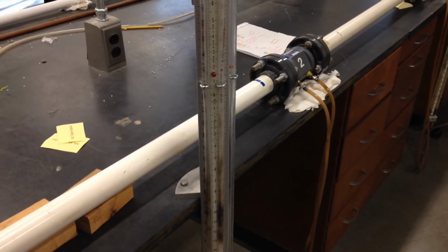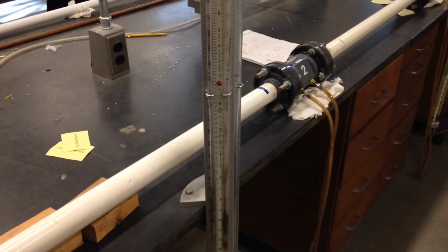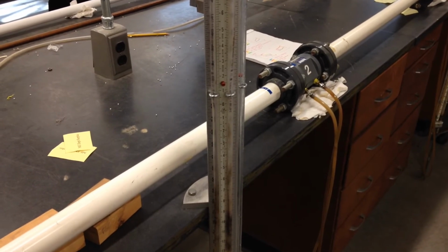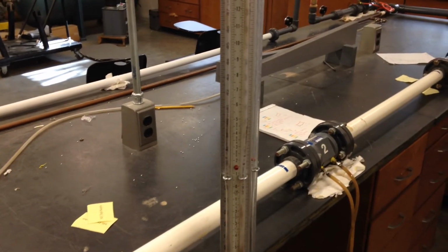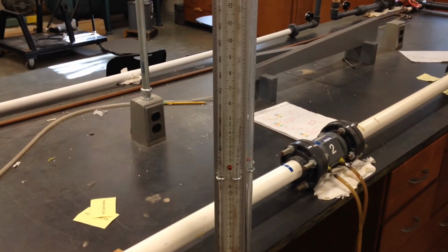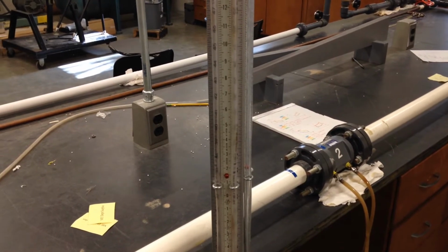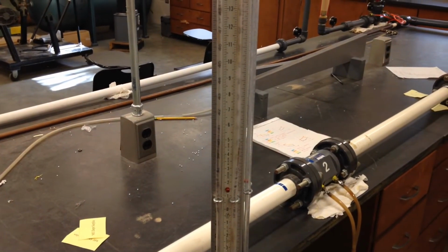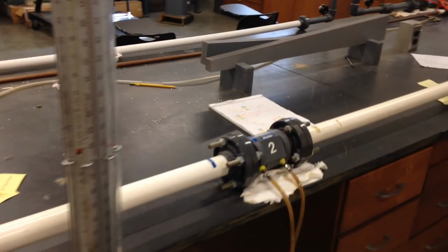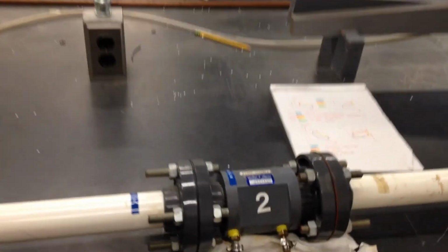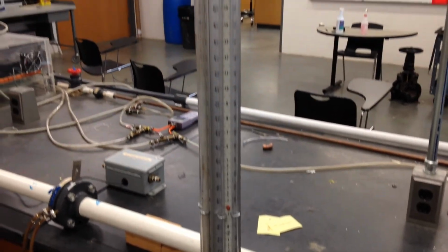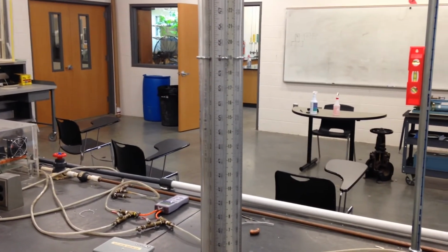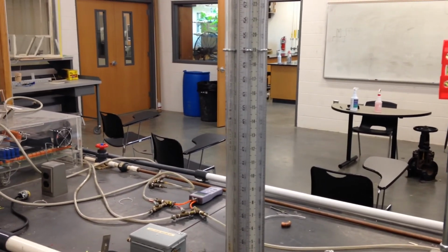Each flow will have 2 different heights of the manometer, and the difference between the 2 is what's important. Don't worry about the absolute height of them. Don't worry about whether one is higher on the right or higher on the left. That just is a function of the way it's hooked up. The second one is the flow nozzle, which I discussed in the lecture, and it has the same type of hookup to the same fluid manometer.